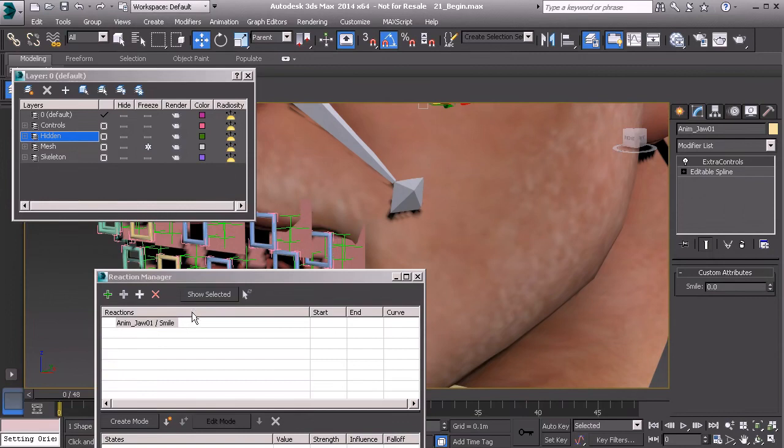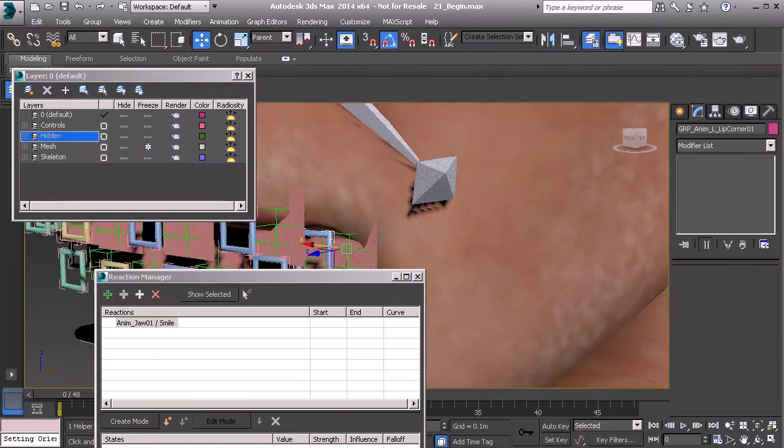So we have a few ways of doing that. We can choose Add Slave, or we can choose Add Selected. I like to use Add Selected because it's a lot easier for us to go in and already have the object selected to add our slave parameters that way. So we'll go in and grab our group, and now we can go ahead and click on Add Selected.